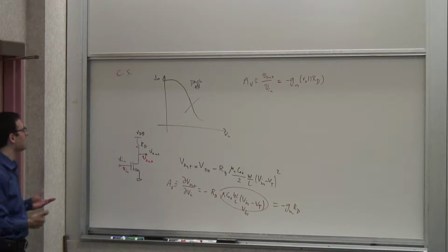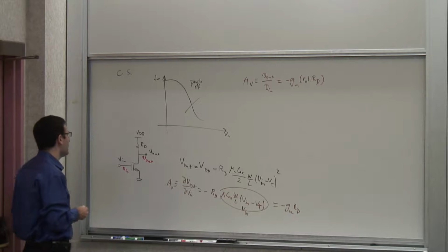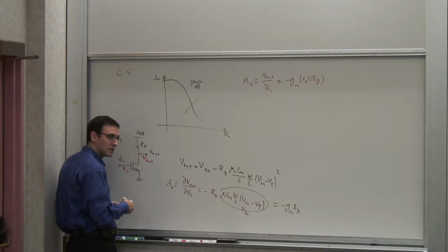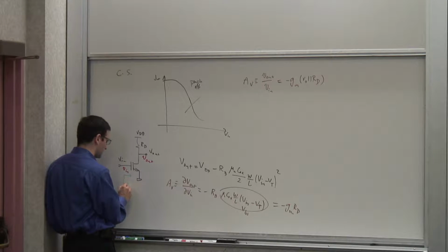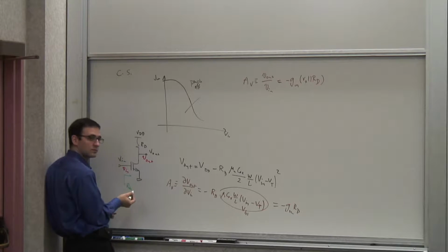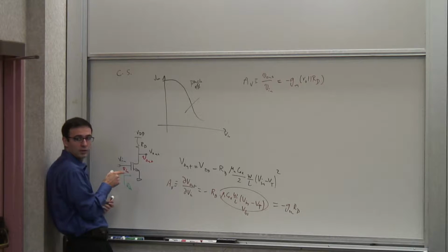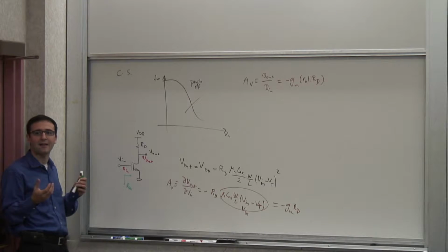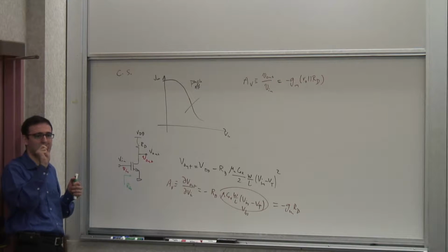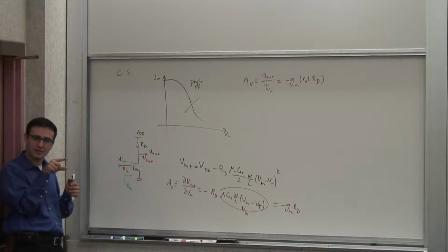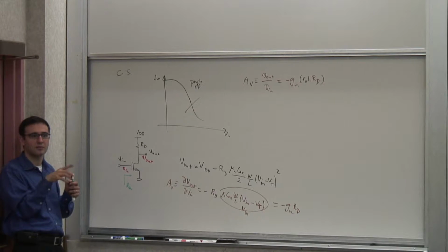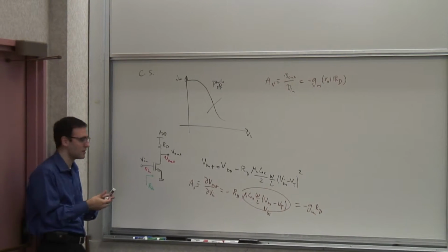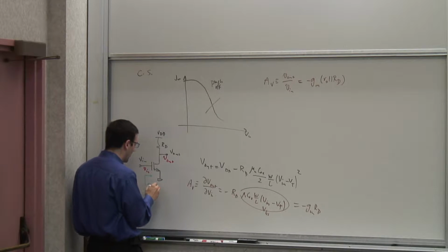And then we looked at the input and output impedances. The input impedance for this thing at low frequencies is what? Is infinity, right? Because there's no DC current flowing, at least based on the classical model, the basic model we have. Of course, we know that once the gate oxide becomes very thin, then there is a gate current, tunneling current as we discussed, and that could result in some sort of resistance. But for now, we say, well, that's very large.